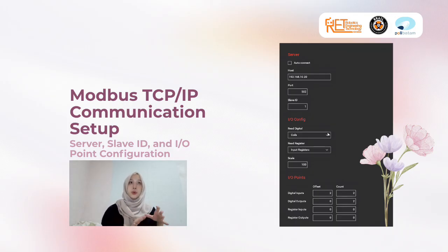This is the host where we put the IP address 192.168.10.20 with port 502. This matches the PLC's IP address from before, since the PLC acts as the Modbus server, and port 502 is simply the industry standard default for Modbus TCP.